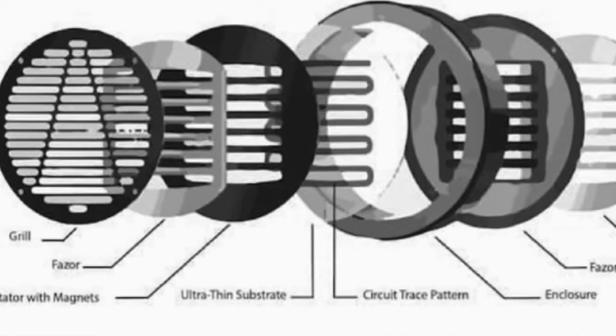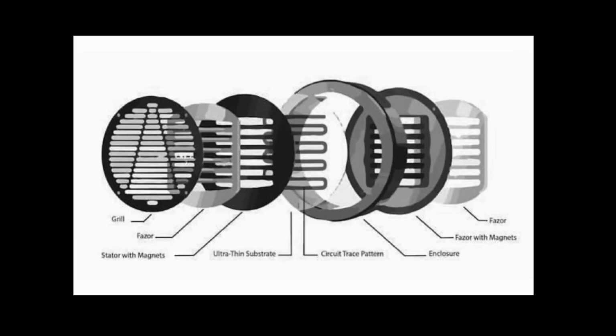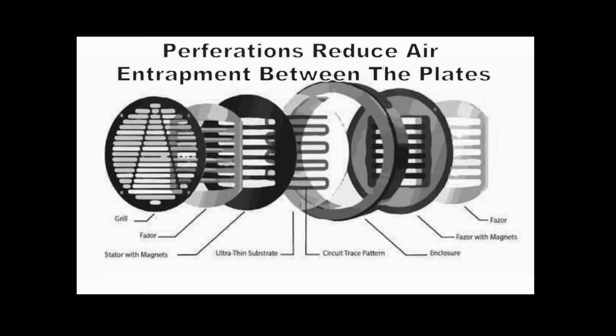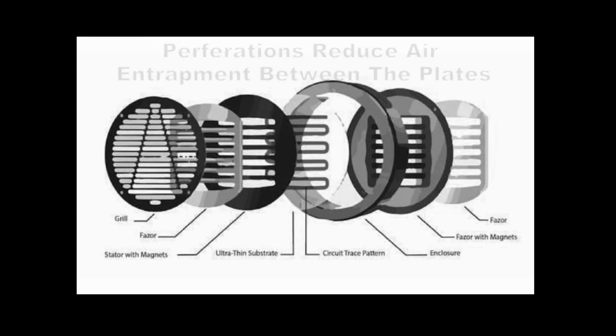Planar magnetic headphones are in the same family as the dynamic type and produce sounds by regulating the electrical flow through a film that's been suspended between magnets with equal magnetic force. The magnets are placed on either side of the electrically active diaphragm material. Upon application of current, the diaphragm gets electrically charged, creating a magnetic field, and when the magnets on either side of the diaphragm react with this magnetic field, it causes the diaphragm to move, therefore creating the sound waves that we hear. In planar drivers, instead of a coil going down the middle, there's a flat film that covers the entire diaphragm.